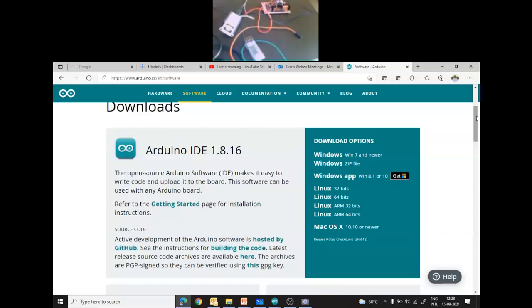Okay. So again, one question is: can you interface a GSM module to the Node MCU board? Yes, because the GSM module has TXD and RXD pins, and our Node MCU also has two ports, TXD0, RXD0, TXD1, and RXD1. So two serial ports are available, so you can easily interface a GSM module with it, no problem. Okay, sir. Thank you, sir.